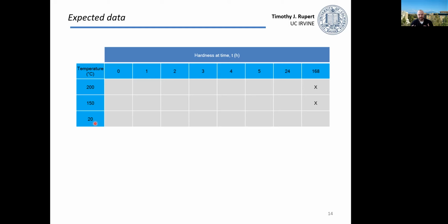So what that means is we need to remember that Celsius is not an absolute temperature, okay? We really want to convert that to Kelvin and think about what temperatures we're working with there. So if it's 600 or a little bit over 600 degrees C, that means it's going to be about 900 Kelvin. And if we think about room temperature, even though it says 20 degrees C, that's almost 300 Kelvin, okay? So even room temperature is about a third of my melting point.